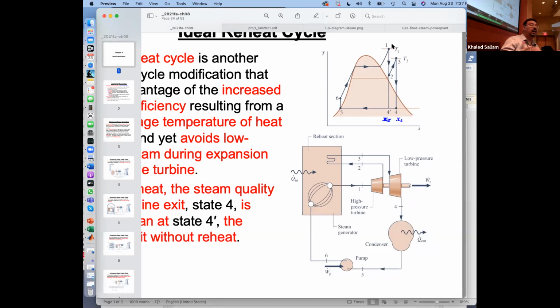You can basically say, I'm assuming no pressure drop through the boiler. But let me figure out if that's a big deal or not. Assuming that length and that flow rate, I know the pressure calculation. What's the pressure drop in a pipe? F L over D V square over 2G, that's the head loss, right? F from the Moody chart, L over D V square over 2G.